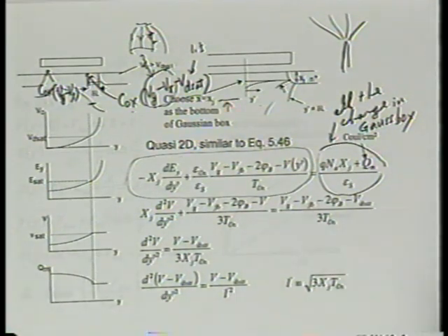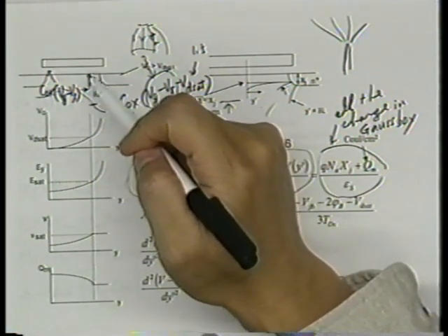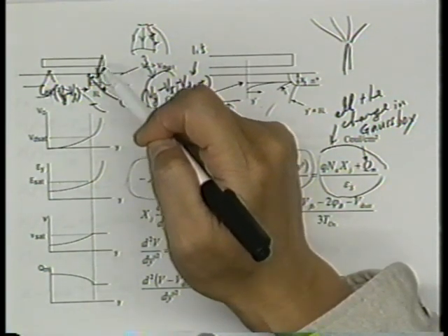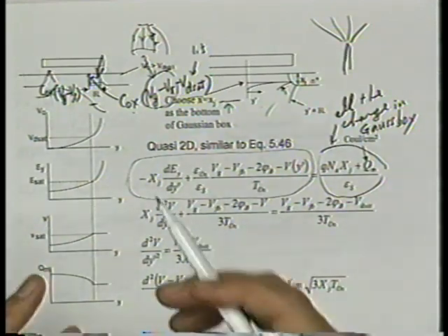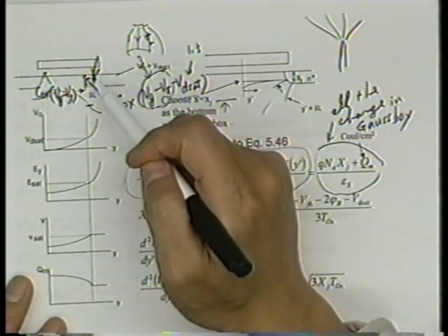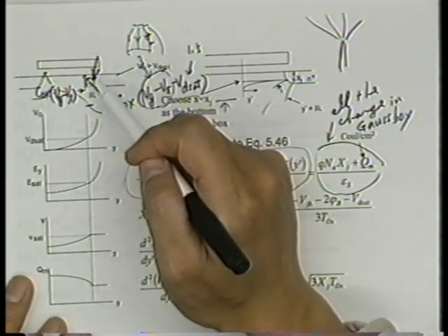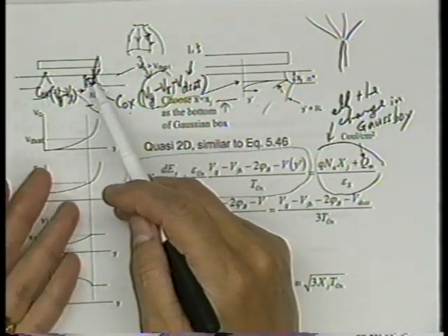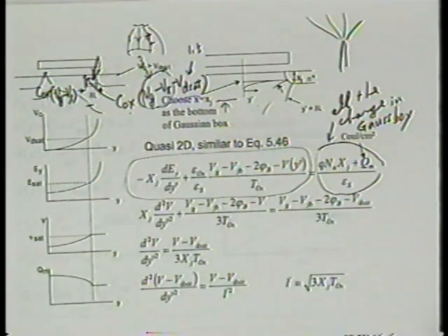Number two, this is the really interesting question. What about the charge density, not so much in volume, but per area, what we call the Q inversion? What about the charge density here, way into the pinch-off region, in fact almost at the edge of the N plus junction? What can you say about the mobile carrier density there?